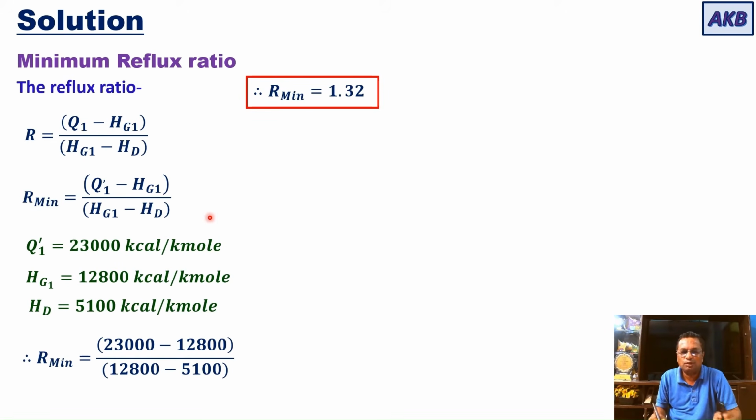So in this way, you have to find the minimum reflux ratio. For finding it, the location of Q, delta D m and delta W m is required. They are located by drawing a tie line that passes through XF and YF. How to get YF? YF is the mole fraction of the more volatile component in the vapor phase that is in equilibrium with XF.